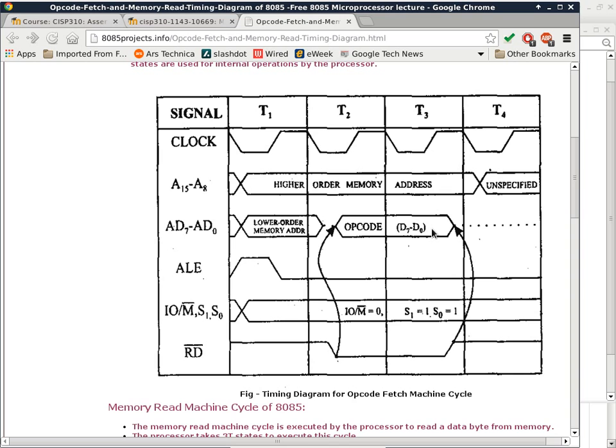Okay, and here's one other thing that I just want to point out. This is a read operation. So how come the read line going low is actually causing this to happen? This is called an inverted, well, not inverted logic. It's called an active low signal. Active low means when the signal is low in terms of voltage, it is asserting that operation. Normally we think when a voltage is high on the line, it is asserting that function or whatever function that pin has meaning for. But in some cases it is inverted. So in this case it is inverted.